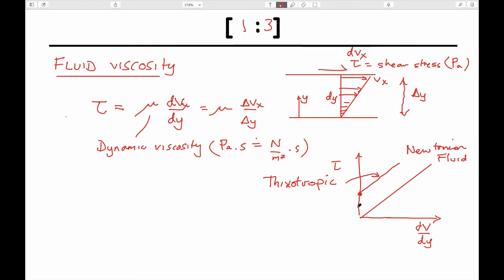And all of a sudden, as you increase the shear stress you apply up to a big enough magnitude, it goes at this velocity. And as you apply more load to it, it goes faster. A Newtonian fluid always goes through the origin. If you apply no stress to it, it has no velocity. If you apply very small stress to it, then immediately it begins to move. The only fluids we'll work with in this class are Newtonian fluids, in addition to working in SI units.